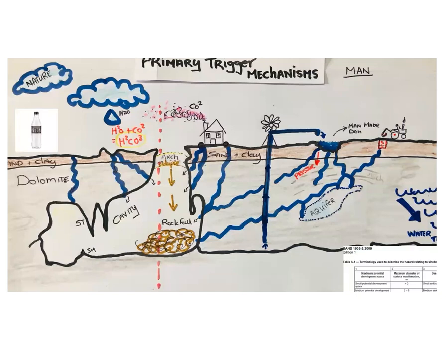Other factors that add to this: you might find that there's a lot of borehole draw off of the water table. So if I can just draw your eyes back to the arch next to the little house. When the water table was nice and high, maybe when there was no man-made infrastructure, that arch may have been supported, and water is incompressible. So it may have been supported with water below it. And as man has drawn off water from the tables below, suddenly you're left with a cavity that's not supported, doesn't have any type of extra support. And then you get things like a rock fall, an archway that falls in, and you're going to have this doline or these cavities that are forming.